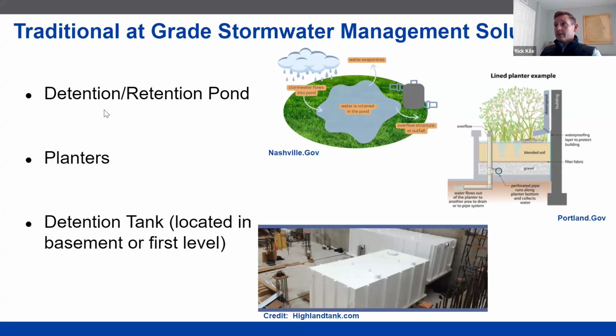So, detention or retention pond. This is a common solution utilized in more rural areas, or less urban areas where we have more access to land, inexpensive land perhaps, and water can simply be put into these retention ponds, or a detention pond, and either released or held and then infiltrates into the groundwater or evaporates, right? Planters, it can start to get a little more urban, a little more density, but planters where we can hold water for a period of time, usually at grade. We can start to elevate those over structure, but then they really do start to become more expensive.